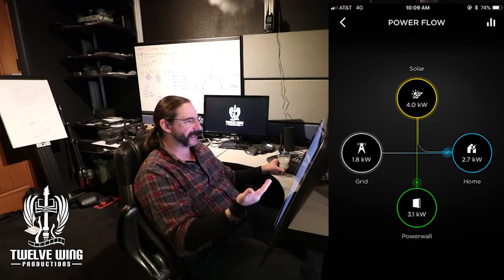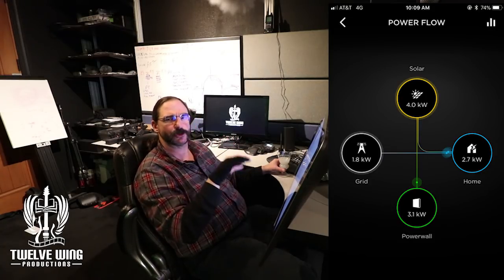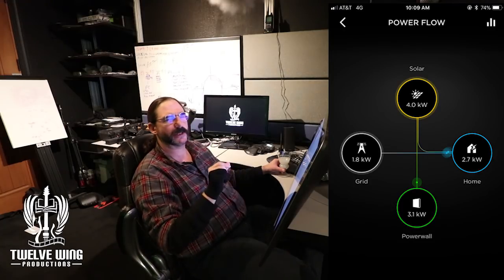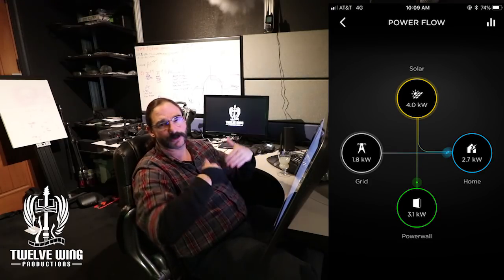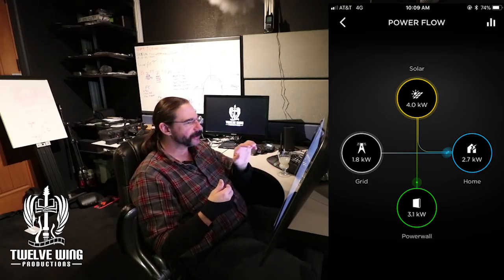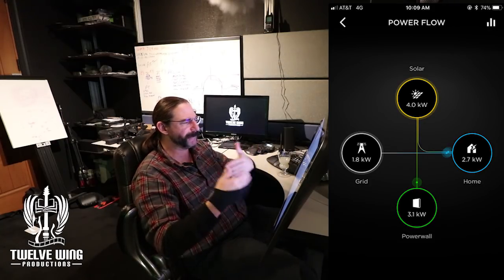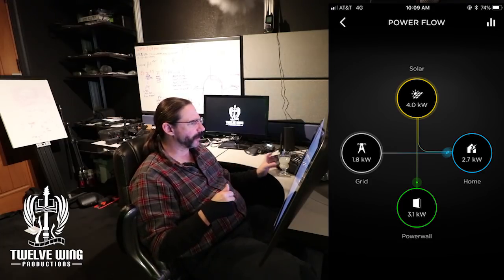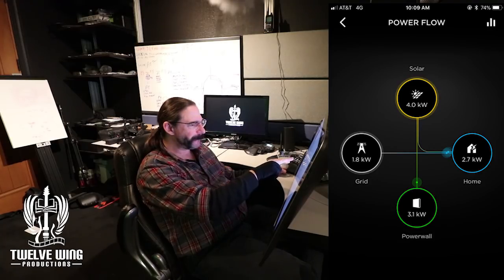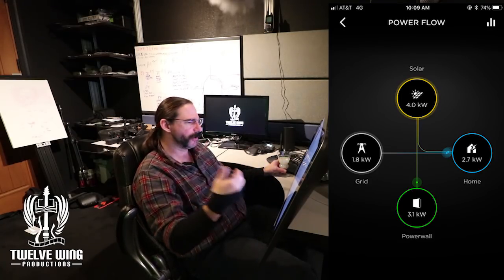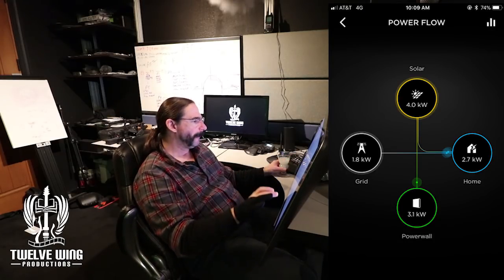I'm using the advanced setting in the software, and I have the section that says reserved for power outage set to 0. I'll show that screen a little later. What that does is it says, okay, how much do you want me to store above all costs? As long as that's 0, it should use the cost savings and make some determinations according to that. Doesn't seem like that's what's going on. And I also have the time of use plugged in, so it knows at what time my power gets expensive. It knows that power is going to get expensive at noon.